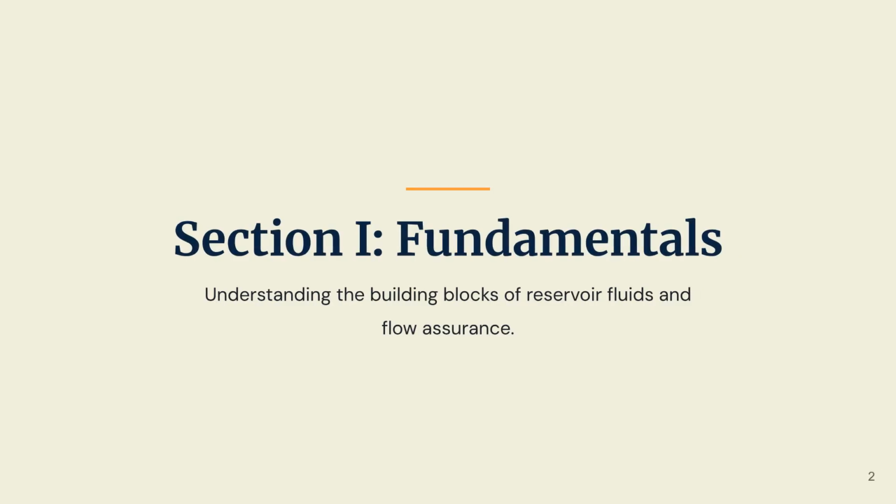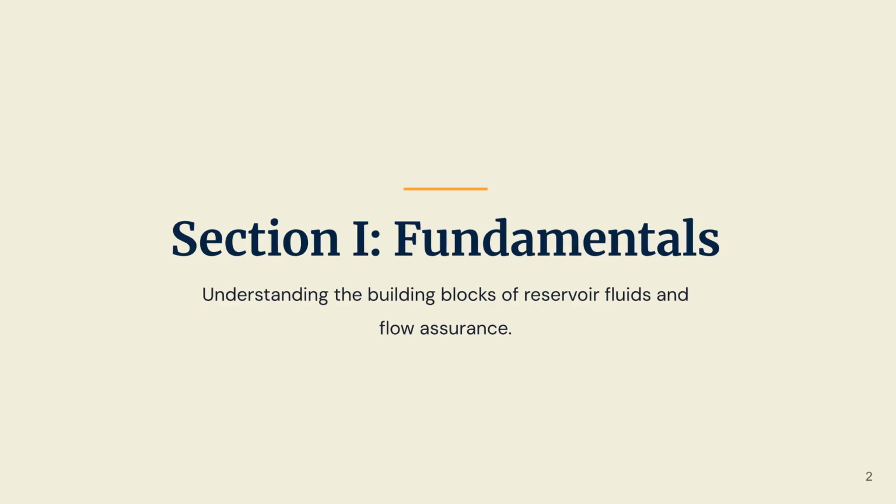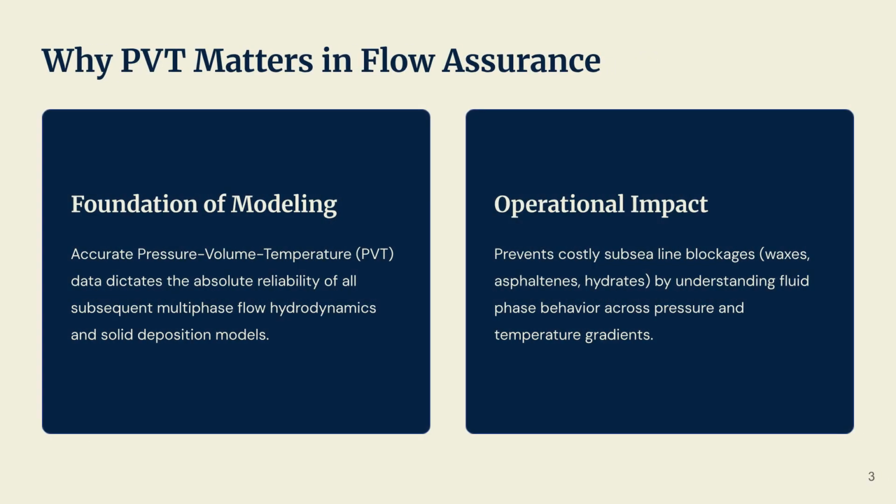In this first section, we will cover the fundamentals, specifically focusing on the essential building blocks of reservoir fluids and their role in flow assurance. Why does PVT matter? Accurate data is the foundation of modeling and is critical for predicting operational behavior, helping prevent costly subsea line blockages caused by waxes, asphaltenes, or hydrates.